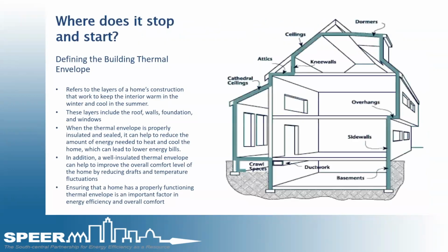So where does it start and where does it stop? Identifying the building's thermal envelope has been one of the key things in training somebody new on how to start an energy inspection. You won't be able to see what you're looking at, but identifying where things start and stop is the very first thing that I try to teach my guys when I was with that third-party verifier on how to approach the home, the dwelling, the building. You've got to identify that and then start looking at the layers that make that up.